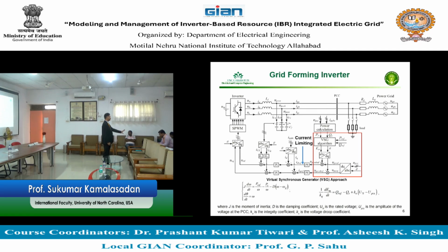Okay, and there are some techniques. One technique to generate these two is by looking at the actual power and the reference power and then generating voltage and angle. Also, you may ask the question, oh yes, we did look at actual power and reference power before too. But there we did not generate voltage and angle. You know what we did? We took the delta.